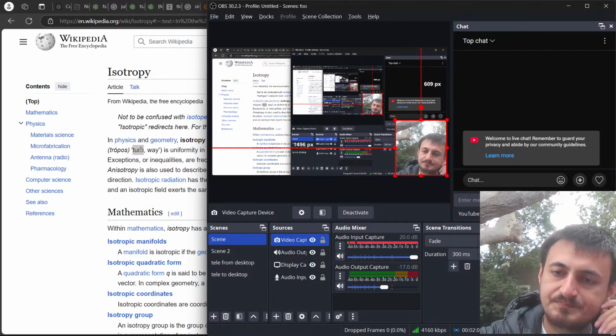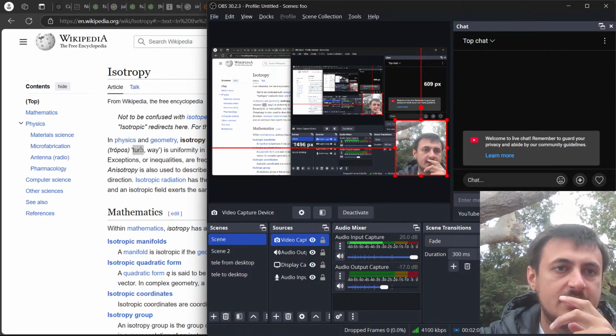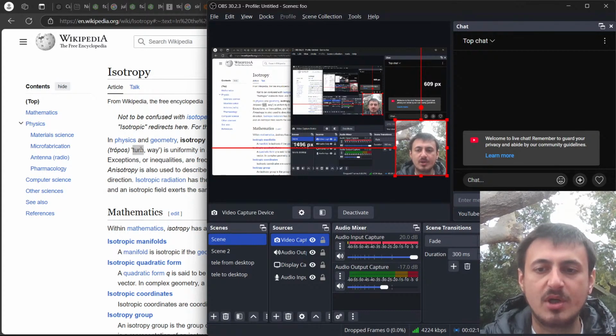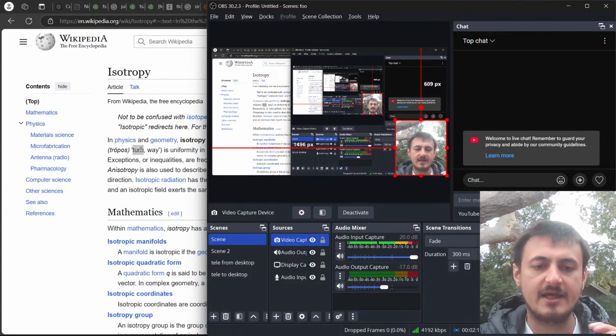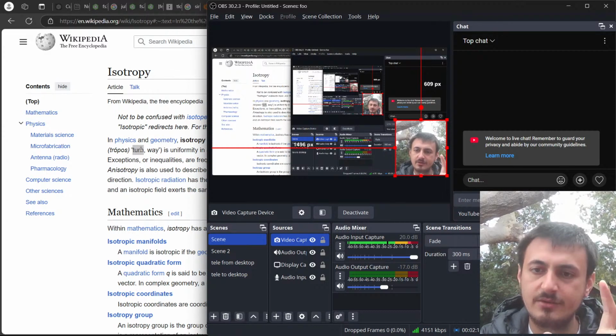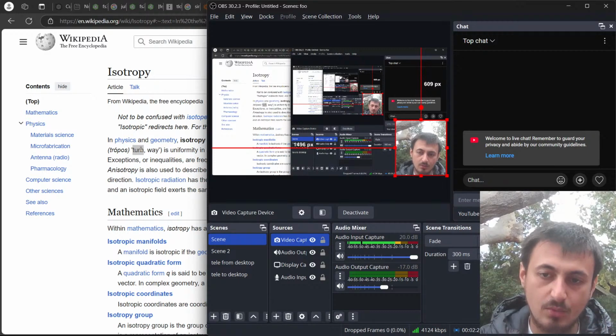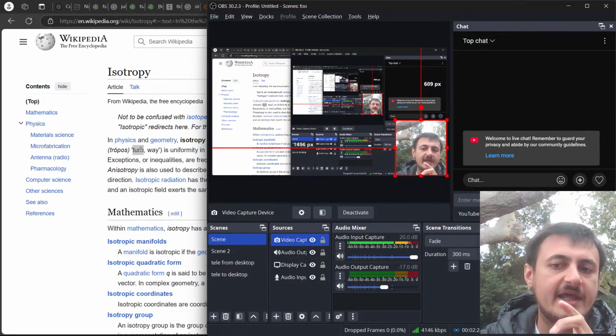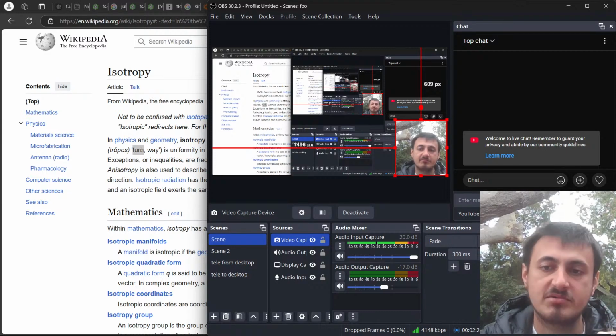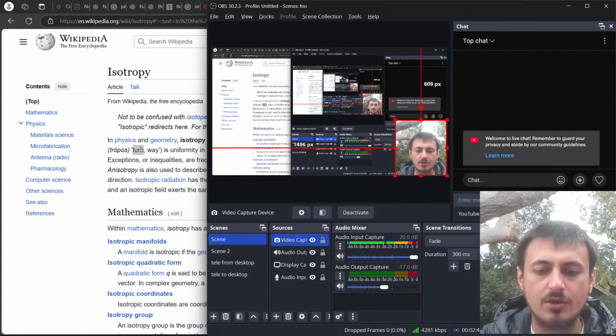And then number two is that people usually print FDM parts at an infill, which means, let's say you're printing a solid block, maybe the outer walls are solid, but the interior is mostly empty space, maybe 85% empty space. So if you were to model the strength of that part as a solid block of plastic, that's totally invalid.